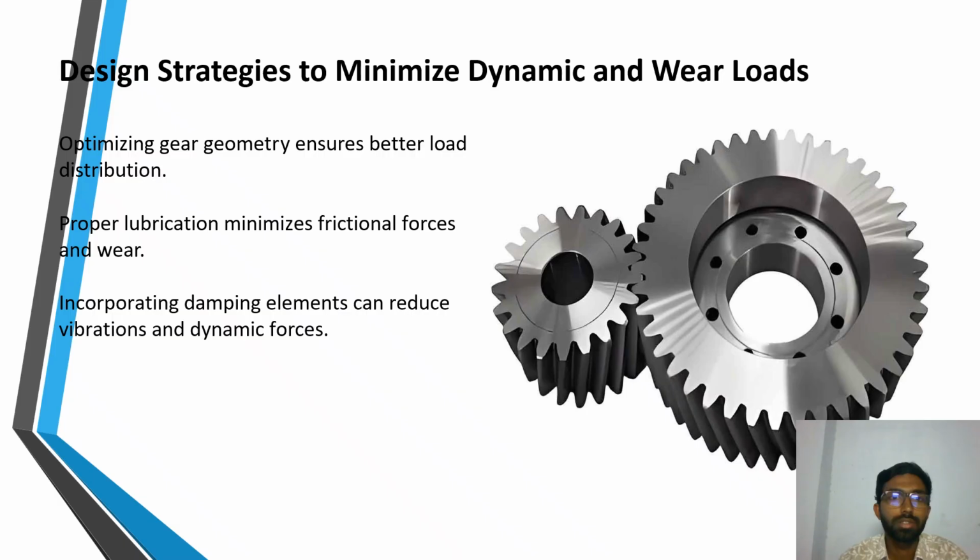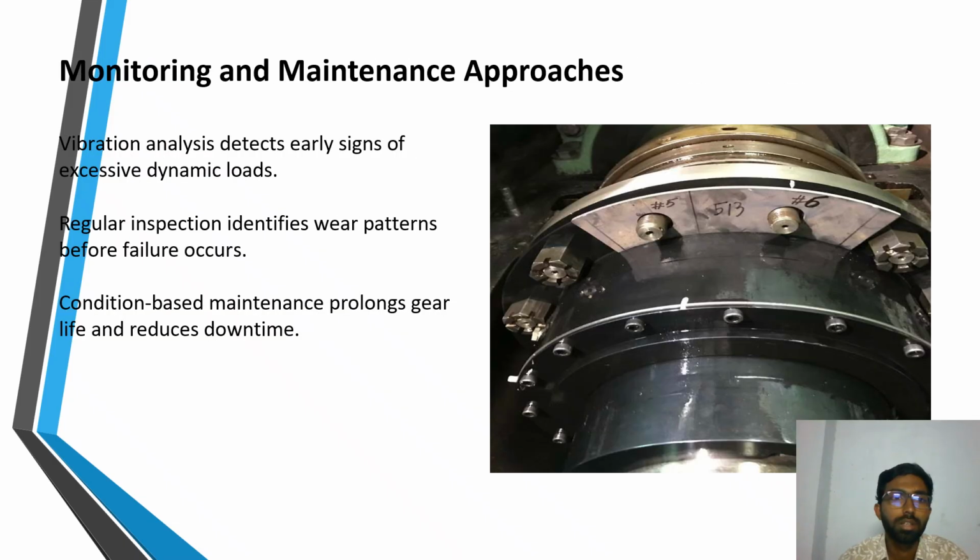Design strategies to minimize dynamic and wear loads. Optimizing gear geometry ensures better load distribution. Proper lubrication minimizes frictional forces and wear. Incorporating damping elements can reduce vibrations and dynamic forces.